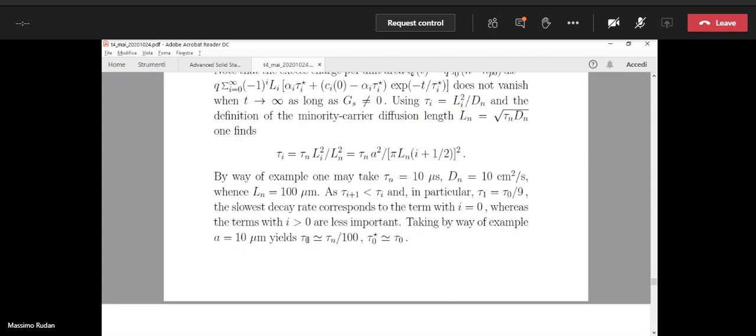If we build an MOS photocapacitor using the epitaxial layer grown over a substrate that is heavily doped, we gain a factor of at least 100 in the sampling time. So we reduce the sampling time very much, so the device becomes much more efficient.